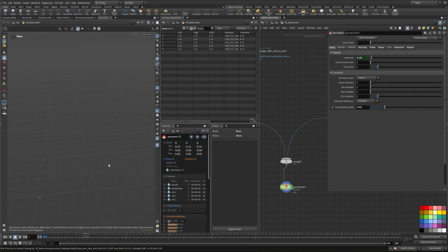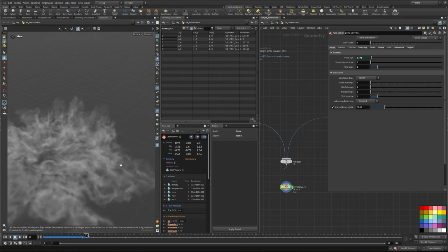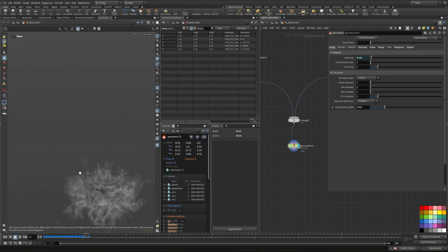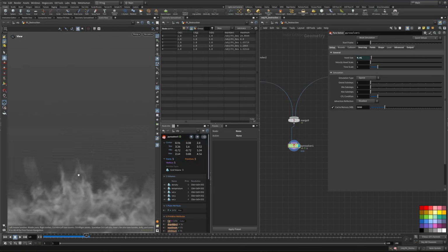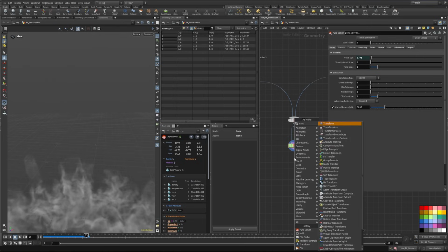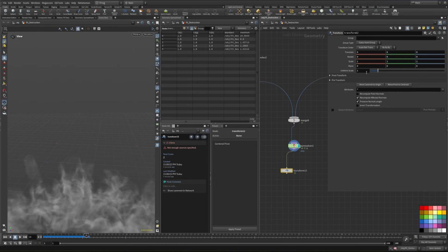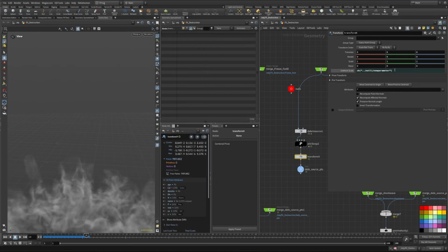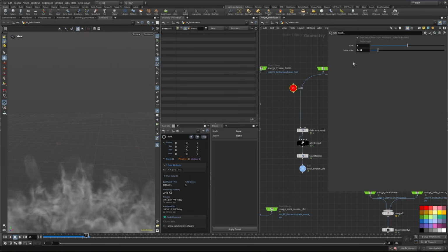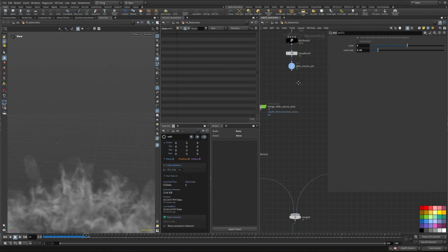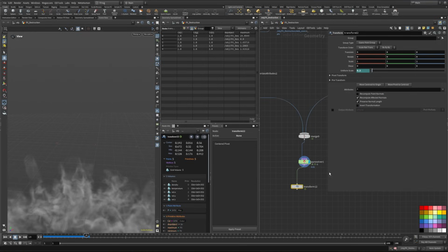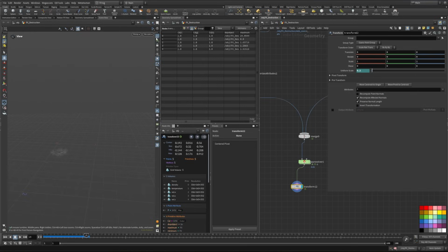Now let's maybe move to frame 13. And now we also got our collision here, and this is looking really cool. Inside the camera we don't see anything because it's so scaled up, but we can change it real quick. So let's use a transform just for now. And we want to use our scale. We can use the scale from here, the parameter, or just copy it out again from here. So copy parameter. And after that one, we're using a slash. And let's paste in the relative reference. So we divide it by this value. Now it's getting back down here.